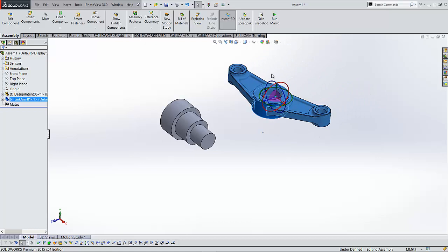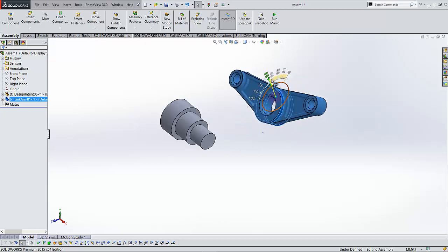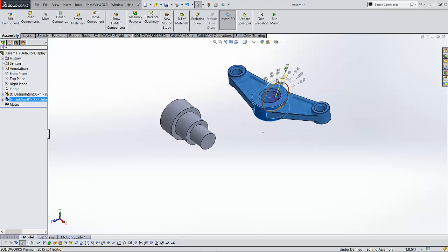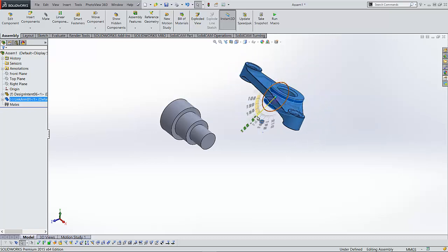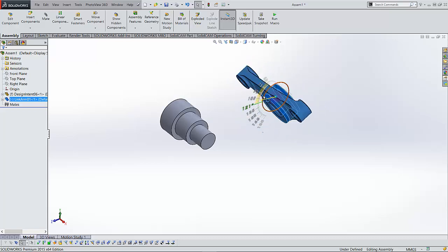So what's remaining? Well, for each axis, X, Y, and Z, we've got rotary axes. So I can turn about the x-axis. The x is pointing out this way. I can turn in a clockwise direction, which is positive, and backwards is negative. And that positive is based on the origin. So imagine you're standing on the origin and you're looking out the positive of the x-axis.